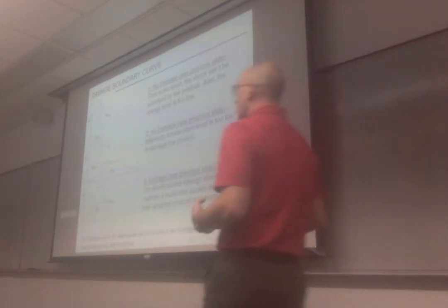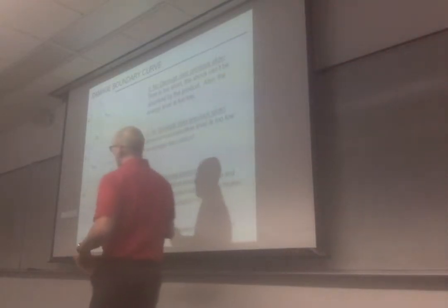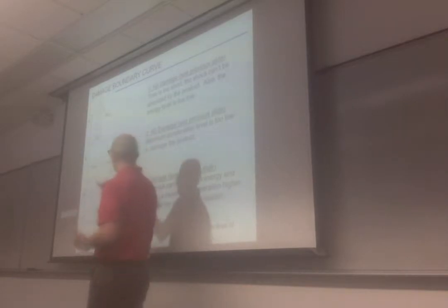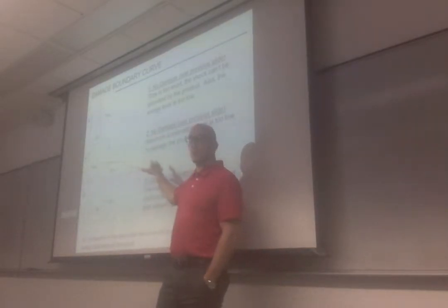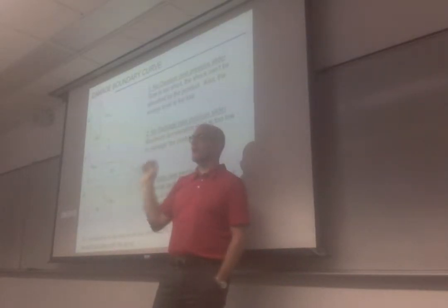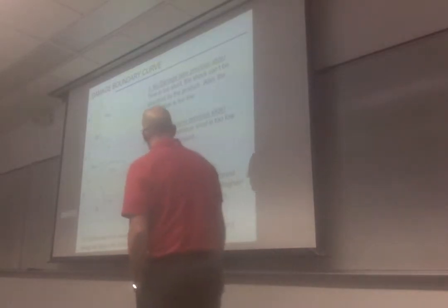This is, in a way, what you want to accomplish using cushioning. You want the velocity change to happen over a long period of time and reach a lower acceleration level, so you have a lot of deformation. I don't want to confuse you by the fact that I talked about cushion. All of these tests are applied on a bare product. That's very important.